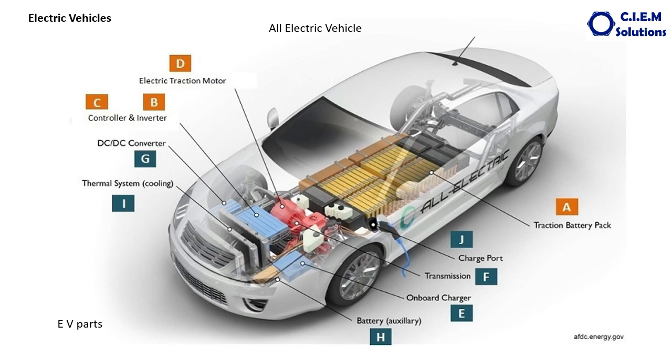Of course, there are rapid chargers. At a few places, they take 30 to 45 minutes to charge the batteries, but it's not advisable because the temperature rises in the system if you keep on doing rapid charging. Rapid charging has to be used only in case of emergency. Let us look at the detailed construction of each and every component.